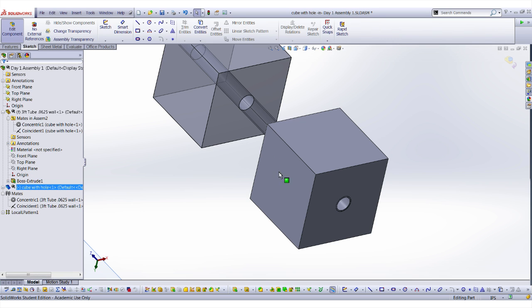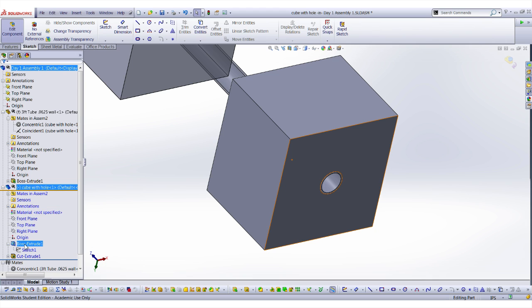So now that edits that to 4, and you can see all of the rest of them changed. So all of them are now 4 inches long. And if we're back in here on the feature tree, we can go down a level and go back into our sketch, and we can edit the sketch.